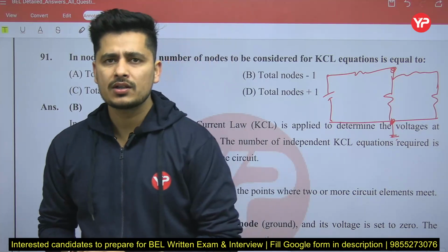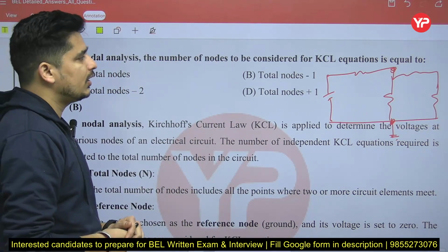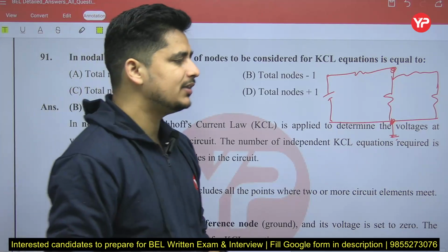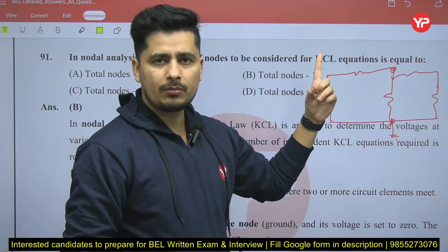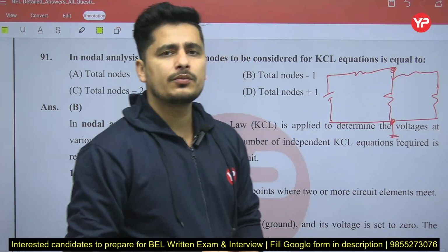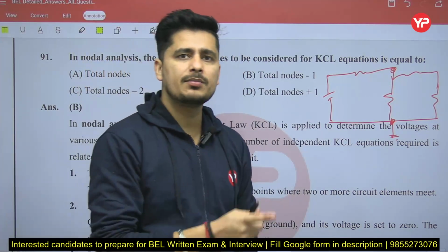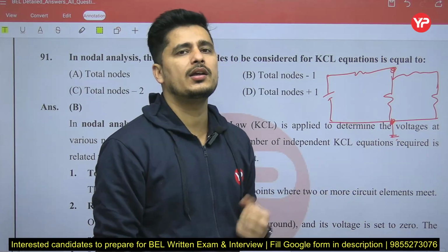Generally we are using the principal nodes; simple nodes we are not considering inside the nodal analysis. When you apply the nodal analysis, you have to find the principal nodes. Let us take, if we have two principal nodes like this, out of these we have to assign one principal node as a reference node. So for the remaining node we can apply the KCL.